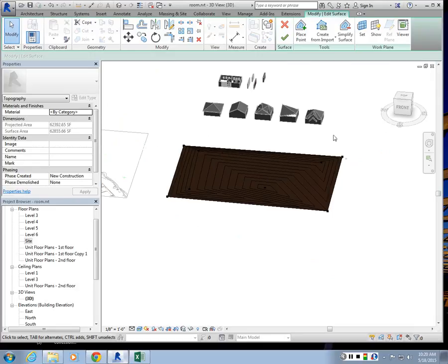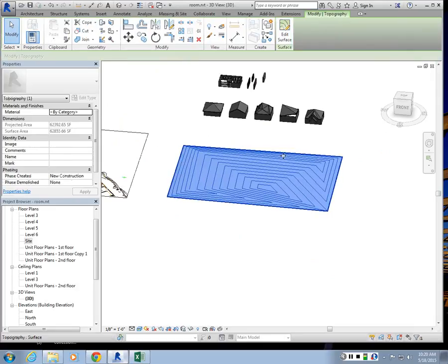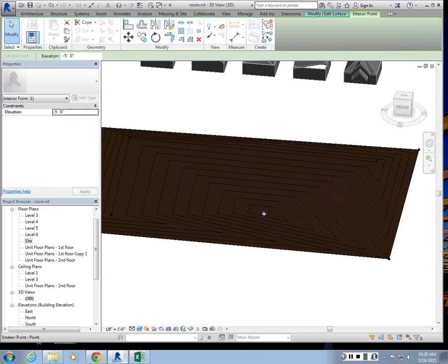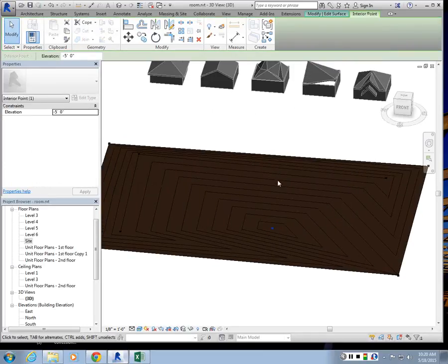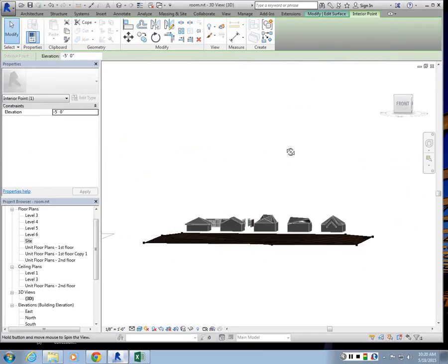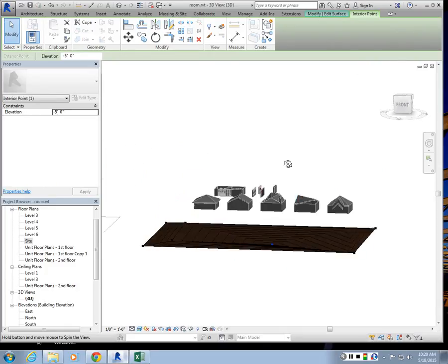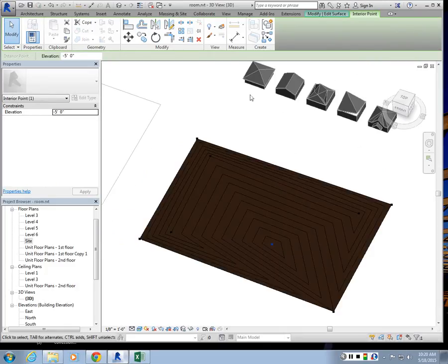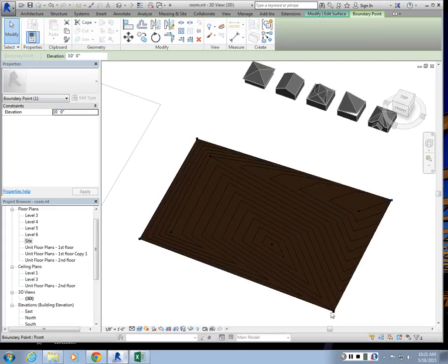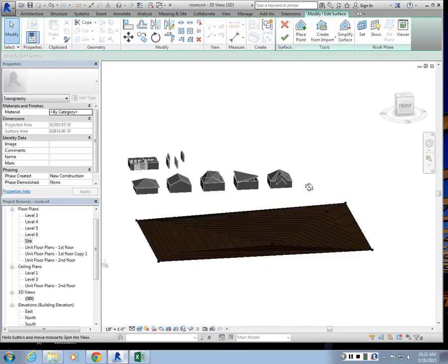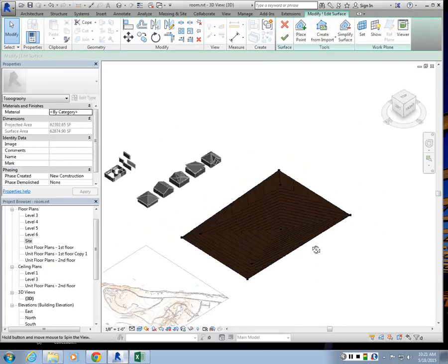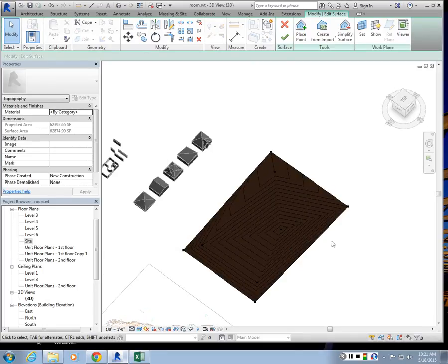No, so you select the topo, edit surface. Once you do edit surface, you can see the control points that you used for interpolation, and you can basically enter the numeric value. So this was at +10, now I made it -5, right? Here this guy is at 5, I can increase it to 10. Maybe this corner is at 10 as well. So this is manually creating the site, right? And it generates the interpolated contours for you automatically.